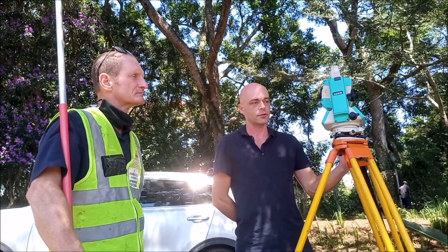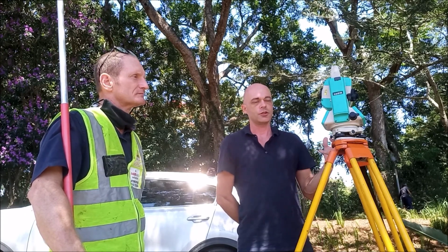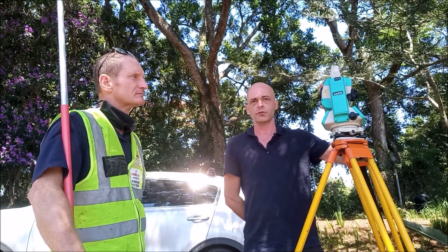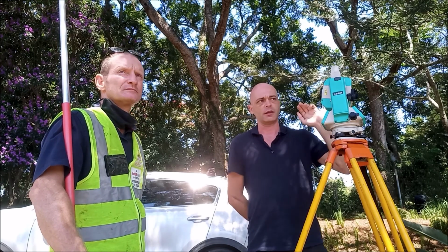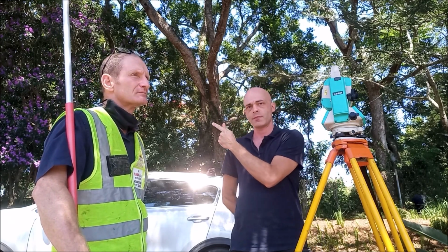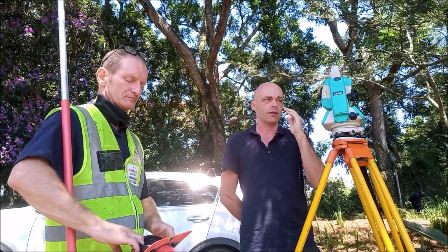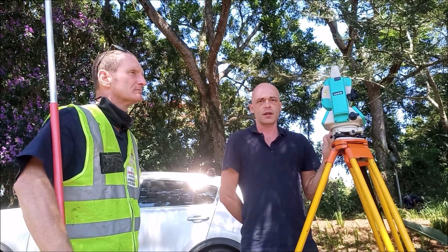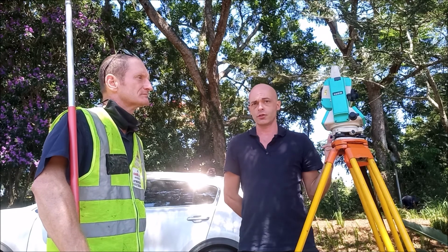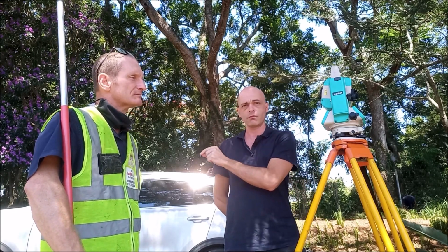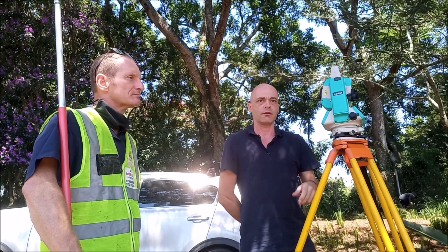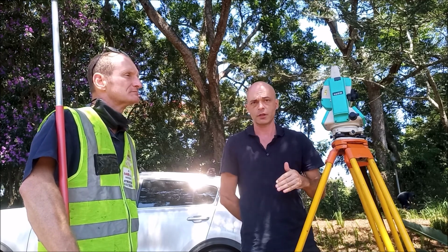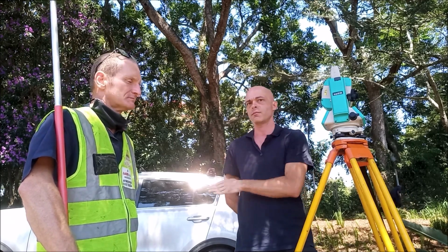So the first thing we're looking at is a total station, and this is used to record different distances. Essentially how it works is there's a laser shining from the total station, and the laser bounces off a mirror, reflects back, and is then read by the total station itself. So the distance is identified by looking at the time it takes for the laser to go to the prism or the mirror and reflect back. From that, the distance can be calculated, and it's also divided by 2 because it's the time traveling from the total station to the prism and back.